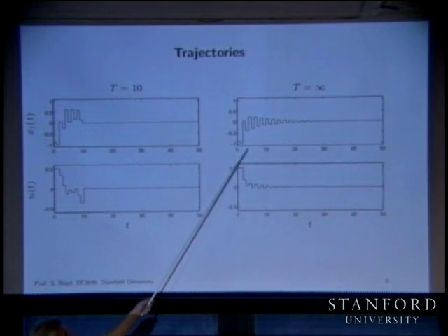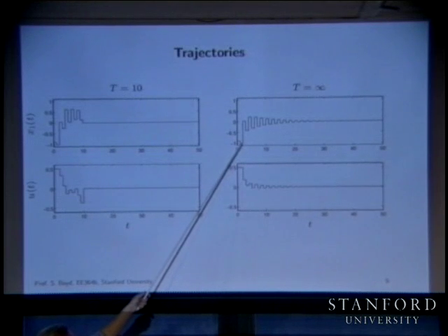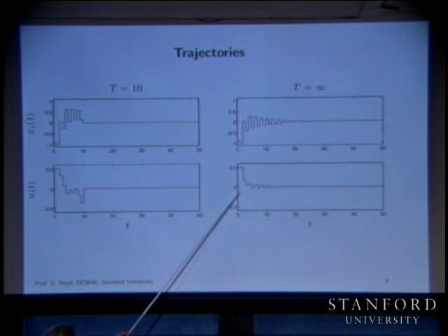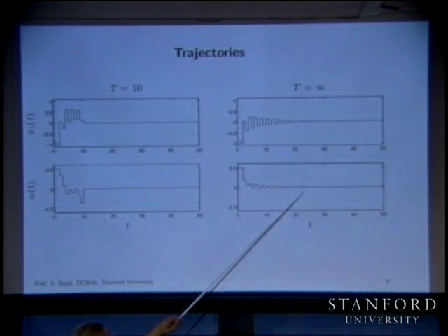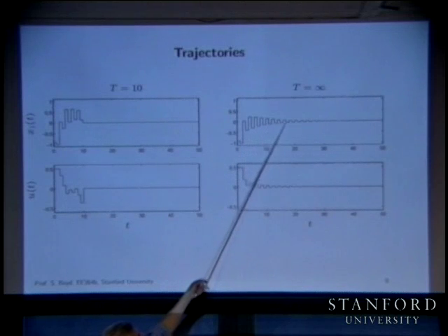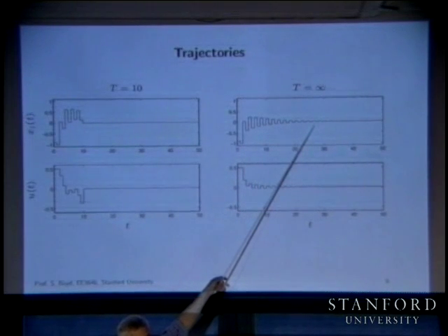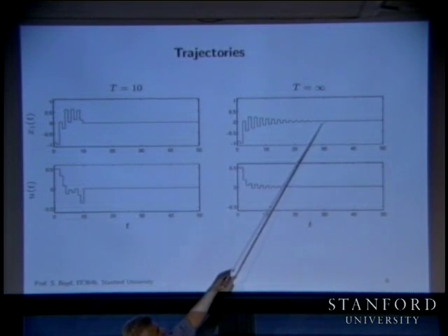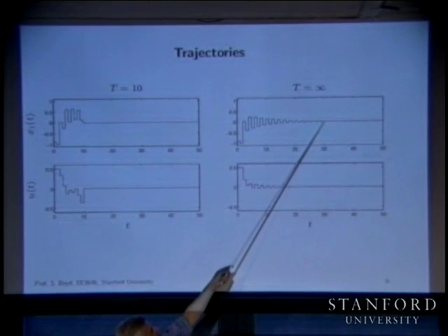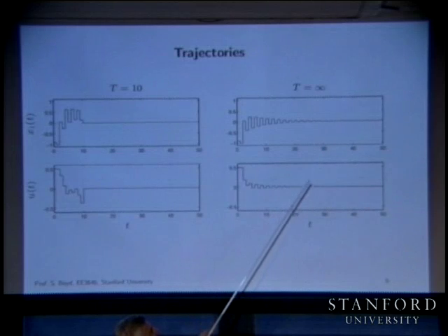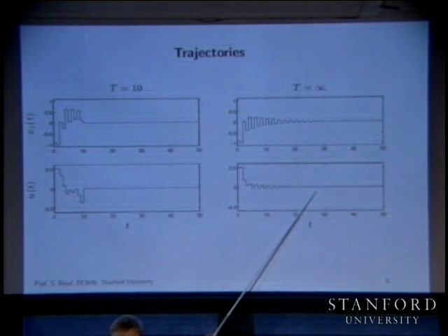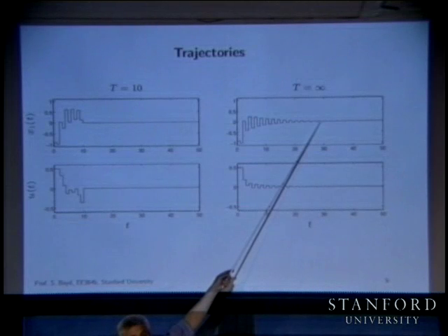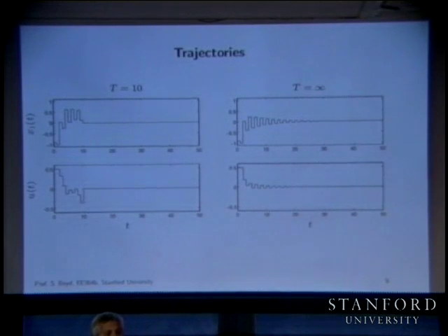So here's the actual infinite dimensional optimal input. And you can see very carefully what happens here. The input looks like this, but then after a while it's dying down like this, and then dying down like that. The point is, this is falling off exponentially. If I tell you, in fact, you have to be 0 at t equals 30, it takes very little perturbation of this input signal to drive the state actually to 0 and not have it be merely small. It takes just minor perturbation. So that's why these things converge very, very quickly.